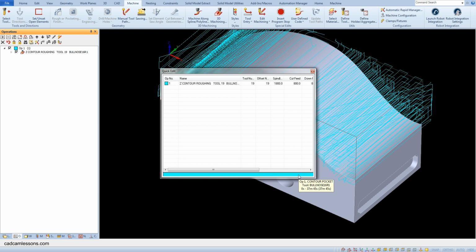And how did it happen that we have the same surface after machining and the time was several times shorter? Alphacam first roughly machined the part with the Z-step of 6 mm, as it was in the first version of roughing operation, and then with the Z-step of 1 mm machined only those steps that remained. So we have a pretty well machined surface and pretty good machining time.